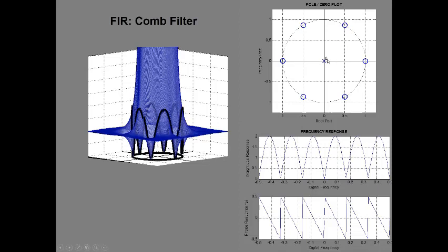If we put a bunch of poles, an equal number of poles in the center, then that holds everything up. And if I have the same number of poles as I have zeros, h of z tends towards 1 as z goes to infinity. That also holds up the edges. And then these little zeros just create notches down, pull down, drag down the rubber sheet at these points.